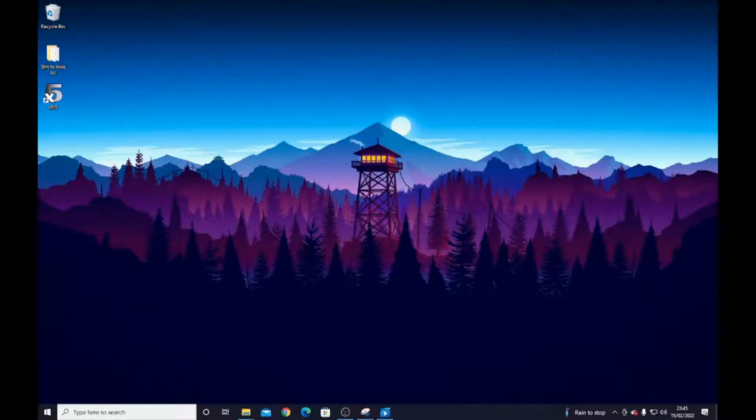There are problems with this simulation when you start to go above, say, Reynolds of 1 million. That applies to jet aircraft, full-scale aircraft, and so on. And there are problems with going higher than Mach 0.3, although there is a correction that you can do to make it go to Mach 0.8.